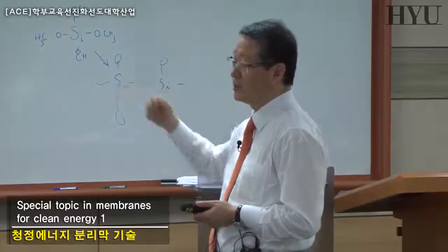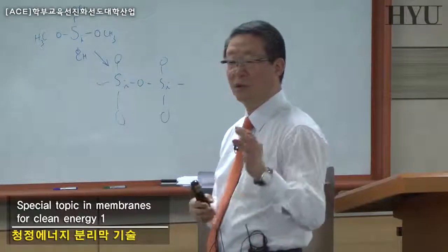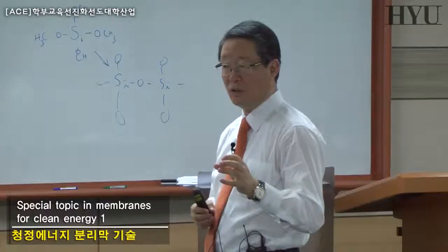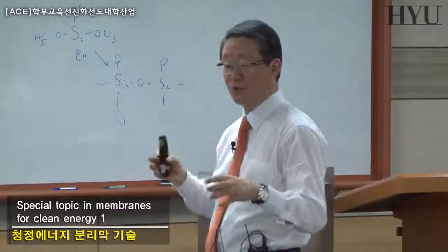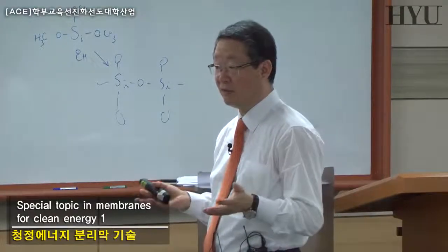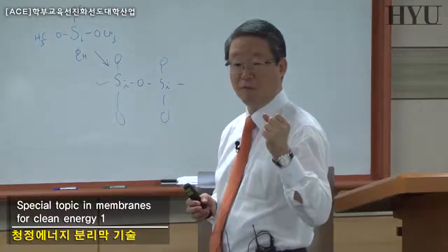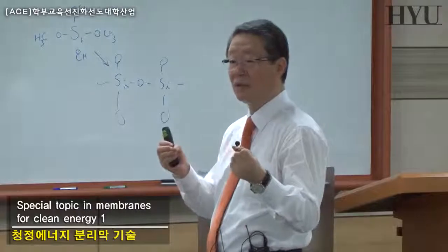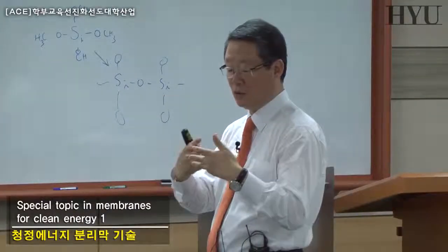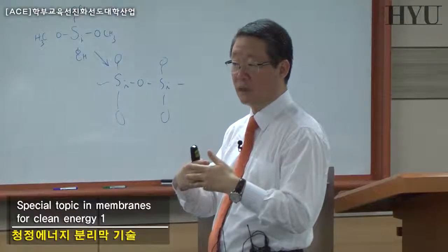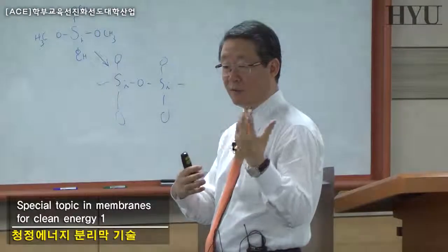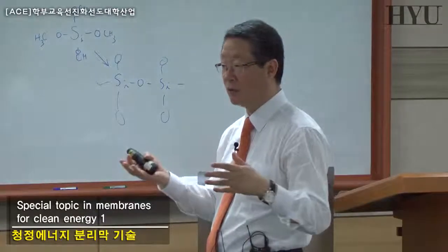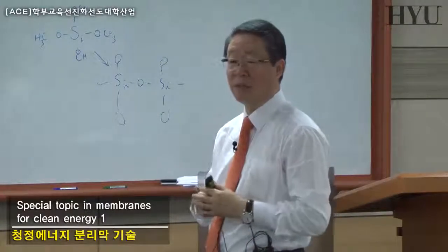If you can make this zeolite structure as well as MOF structure, because of the high microporosity, you can use this MOF or ZIF or whatever by itself as a membrane material. But if you can mix this microporous inorganic or organic material with the conventional polymeric structure, you can combine them together and utilize the microporosity of those materials in the non-porous conventional polymer and make the mixed matrix membrane